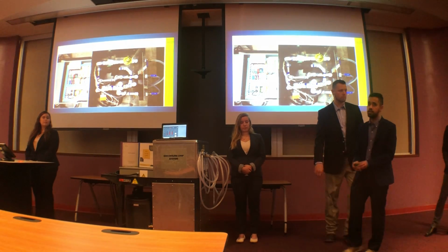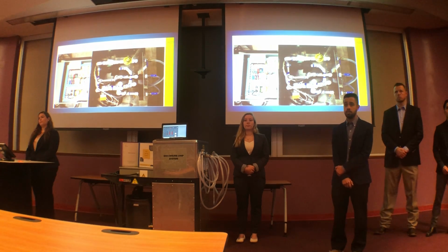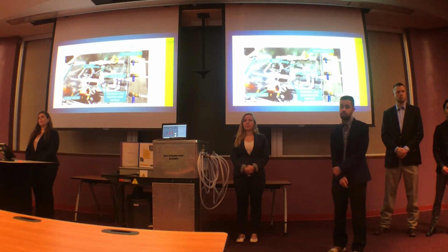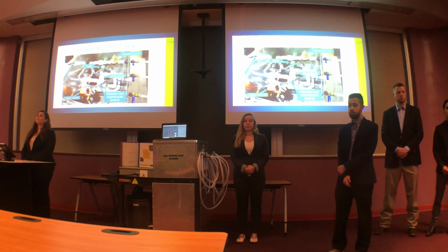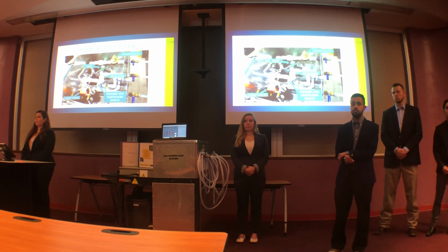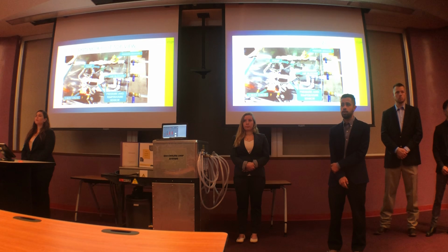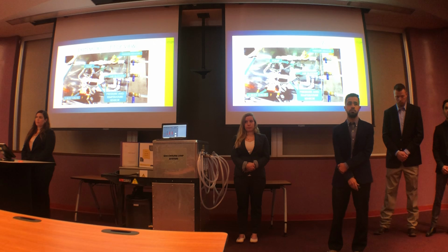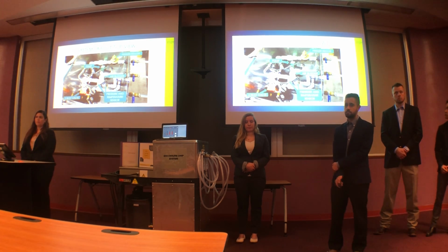For our final design, this is the final prototype from the top view. On the left-hand side, we have the electric panel, and on the right-hand side, we have the piping system. For the piping system, the system is provided by a pump, which controls a steady pressure, and we also have a pressure reducer and 3-way valves to control the flow. We also have an air bleeder for safety purposes, and the system is equipped with temperature sensors and pressure sensors throughout.